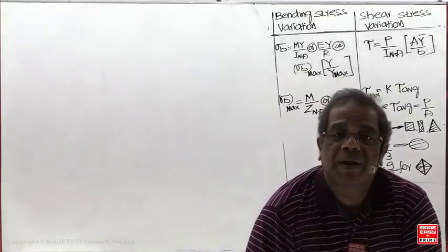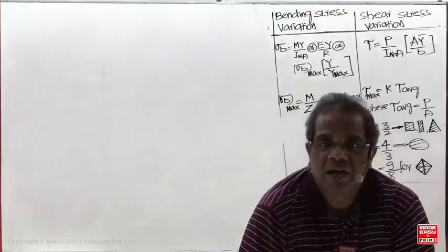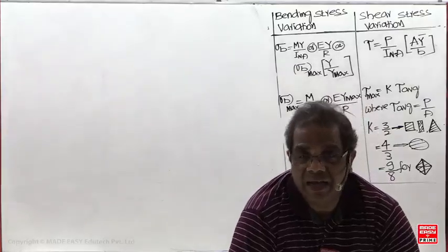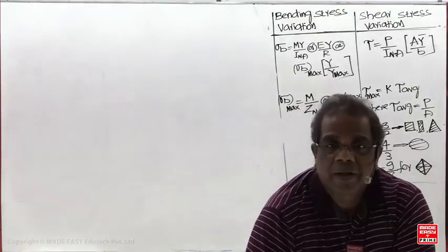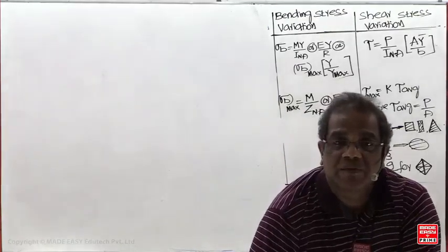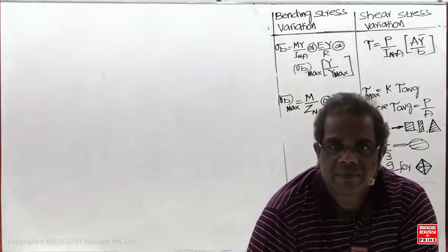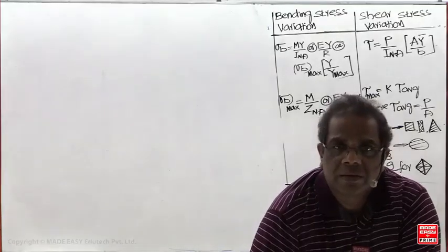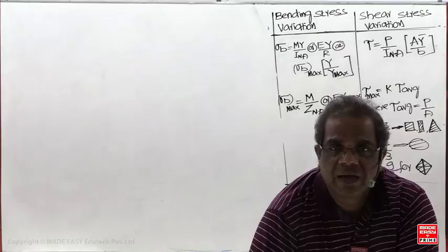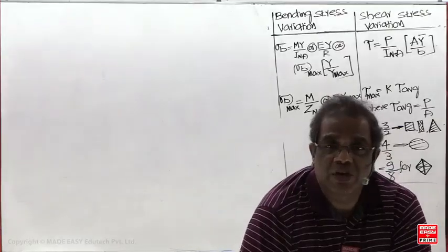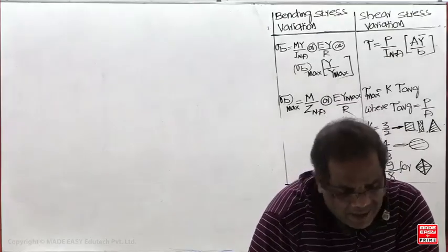Right side or left side depends upon the beam being in sagging or hogging. If you take the sagging case, the top is compressive, and in Mohr's circle the tangent to the y-axis is on the left side. In hogging, the top is tensile, so Mohr's circle is tangential to the y-axis on the right side.